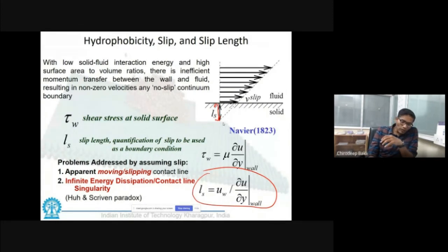So typically, in order to obtain minimum pressure drop, we try to smoothen the surface. We try to polish the surface, making it very, very smooth, so that the frictional or viscous resistance is least. However, that doesn't ensure that my flow would occur entirely for free, because there needs to be some additional pressure gradient that needs to be given.